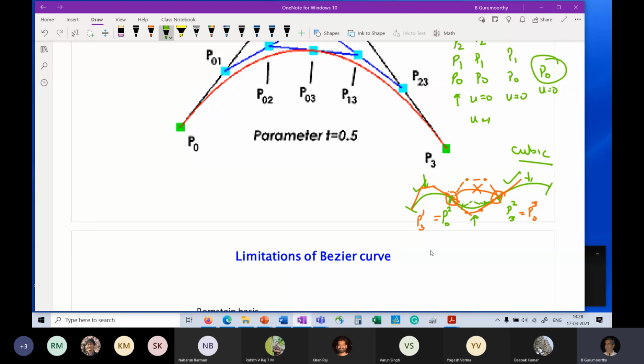So that is a possibility that instead of trying to somehow get this hump in a Bezier curve, the designer will split it from here to here as one curve, here to here as another curve, and the last one as another curve. And while that is a correct solution, you have said what the problem with it is: you have unnecessarily increased the number of curves that you have to manage, right?